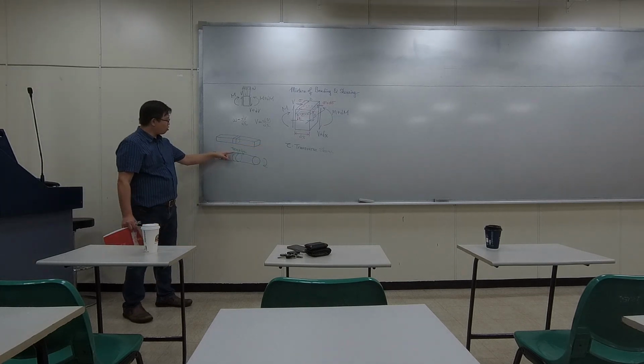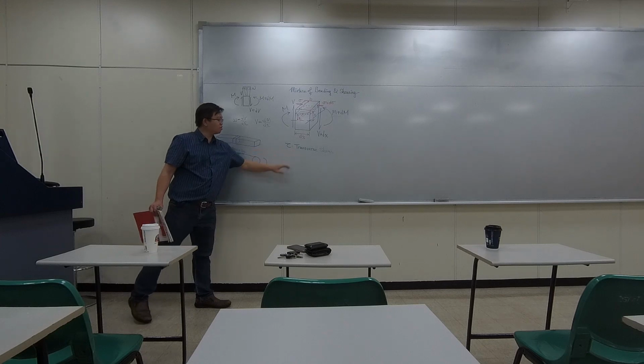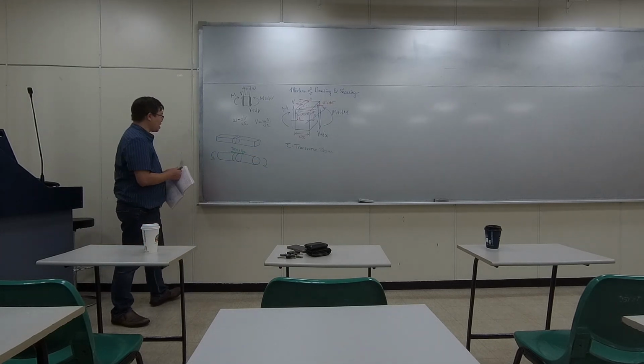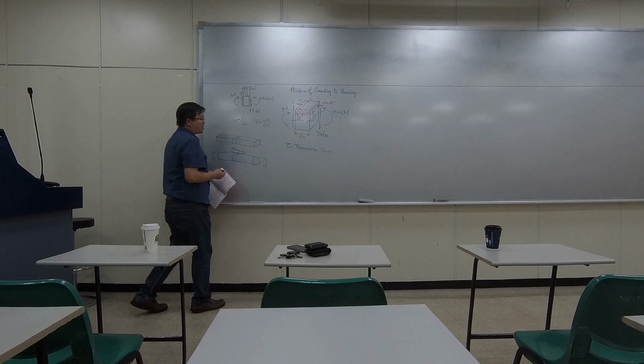So when we are only talking about the stress condition at this position on the top, we don't need to worry about transverse shear because it's 0. However, in my exam, we were talking about the point on the side. When we do that, this plays a role.